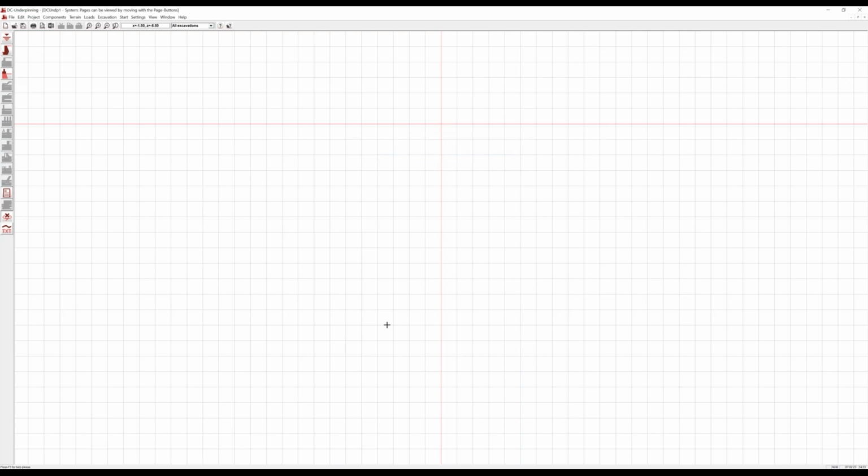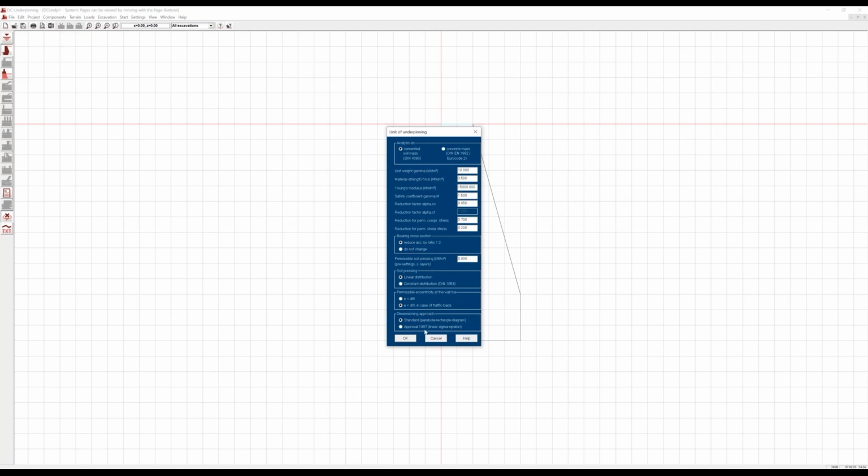Now, if you compare to the program DC-Pit, where we have foundation pit walls, the input is quite similar, but in this case, we don't only draw the gravity line of the wall, but for these underpinnings, we have a certain shape of the wall. So this might be an arbitrary shape, for example, with a larger thickness here in the soil. There might be some larger thickness here. And if we close this polygon, we have the shape of the wall.